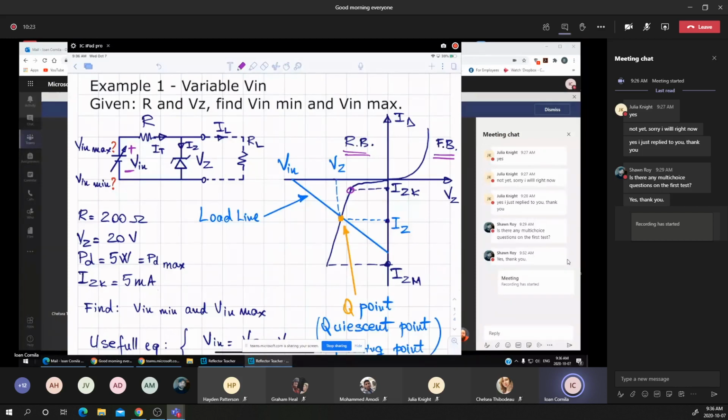In order to place the diode in the Zener mode, or in the tunnel or avalanche mode, we must have the voltage applied to it greater than the VZ. If I choose the VZ, the voltage across the diode, for 3 volts, 5 volts, 10 volts, 20 volts, and so on, the minimum current that must be maintained is the IZK. The maximum current is limited by the maximum power dissipation of the diode.